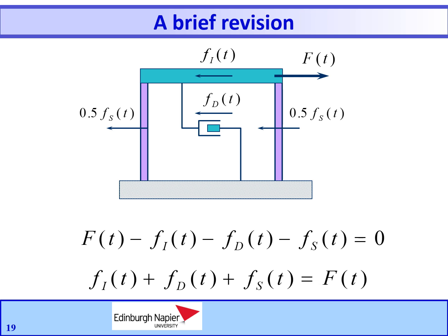Alternatively, having been trained to think in terms of equilibrium of forces, we as structural engineers may find D'Alembert's principle of dynamic equilibrium more appealing. We can then create the free body diagram of this structure at time t, with the mass replaced by its inertia force. In either way, setting the sum of all the forces equal to 0 gives us the derivation of the equation of motion.